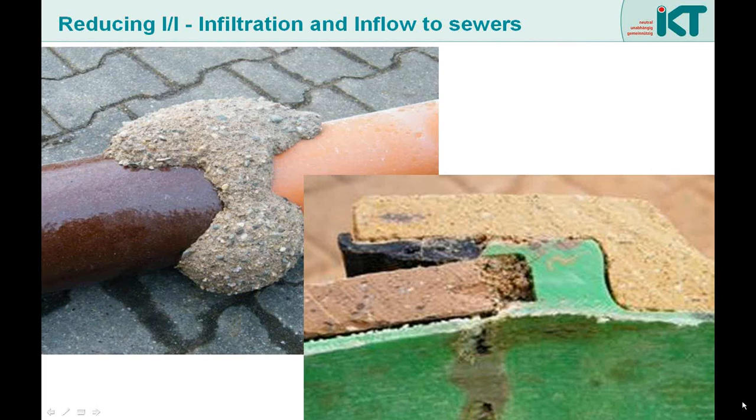The problem is that if the groundwater level rises, we get buoyancy, uplift effects in the soil and the pipe system. And if the liner can't slide along the pipe surface, then even minor movements of the joint can lead to large strains in the liner. The liner bridges the gap at the joint, but it is just a small part of the liner that stretches under the expansion of the gap. So in consequence, the strained liner will crack and groundwater gets into the system again.